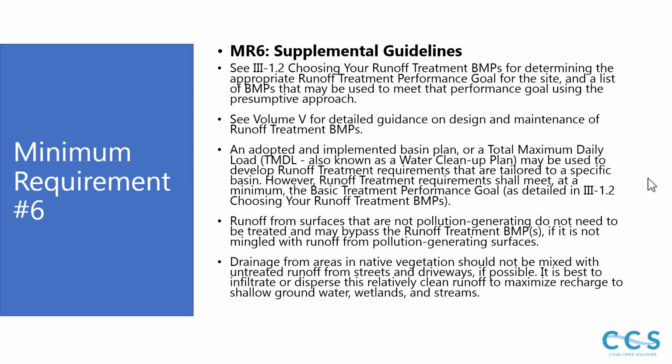Supplemental guidelines C3-12, choosing your runoff treatment BMPs, for determining the appropriate runoff treatment performance goal for the site, and a list of BMPs that may be used to meet the performance goal using the presumptive approach. See Volume 5 for detailed guidance on design and maintenance of runoff treatment BMPs. An adopted and implemented basin plan, or total maximum daily load, TMDL, also known as the Water Cleanup Plan, may be used to develop runoff treatment requirements that are tailored to a specific basin.